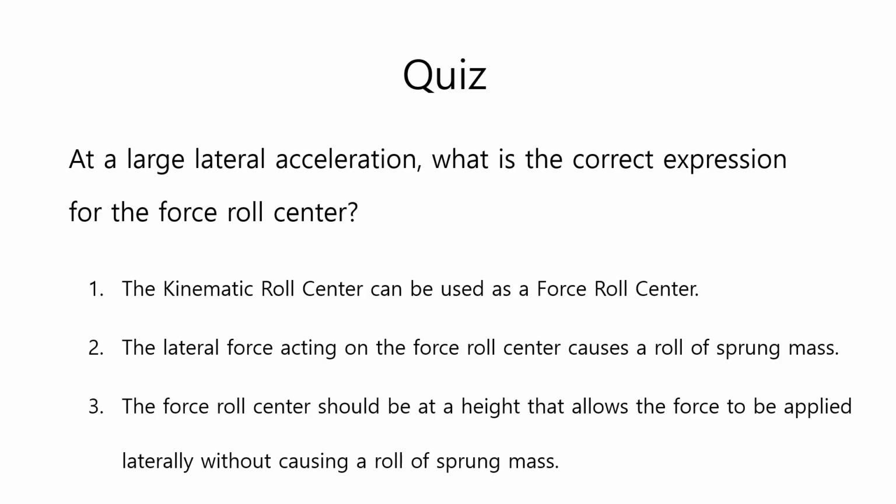Let's take a quiz. At a large lateral acceleration, what is the correct expression for a force roll center? Number 1. The kinematic roll center can be used as a force roll center. Number 2. The lateral force acting on the force roll center will cause a roll of sprung mass. Number 3. The force roll center should be at a height that allows the force to be applied laterally without causing a roll of sprung mass. Please choose one of these answers.